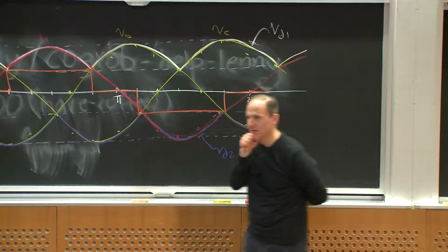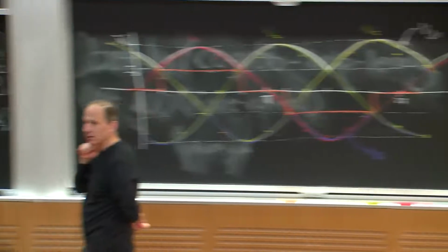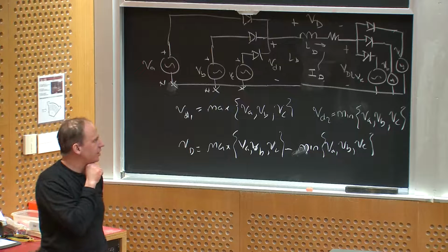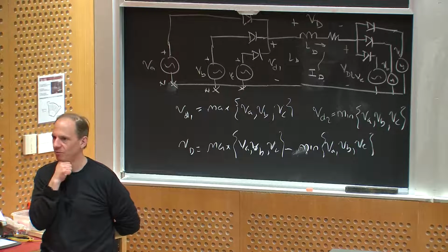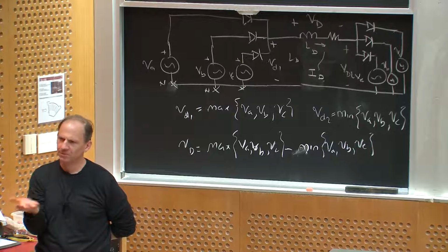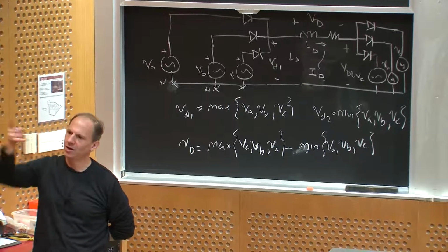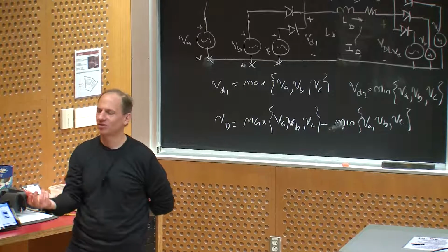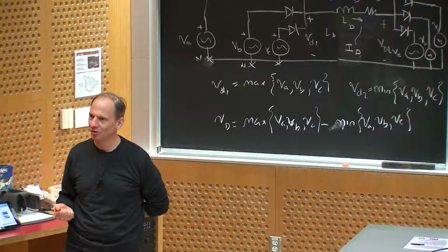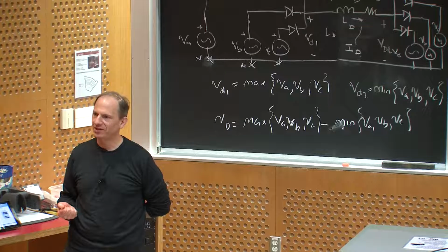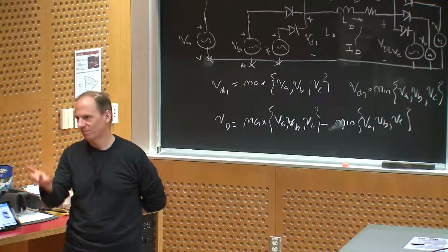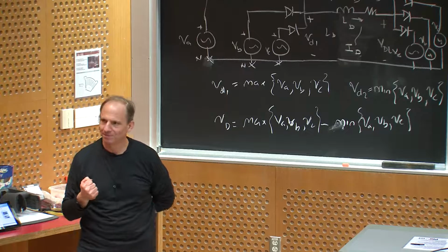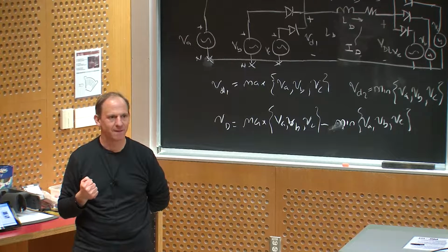I have a question about power factor. If the power factor of the phases are different, is there a notion of aggregate power factor? Well, if the phases are balanced, then they're all the same, and that's the idealized case. When you're talking about power factor, you really only talk about one port of the circuit. If you had an unbalanced situation, it's more complicated, and you can start looking at the power factor of the different phases. But generally, let's keep it simple and say everything's balanced, which it should be if it's working right. Other questions?